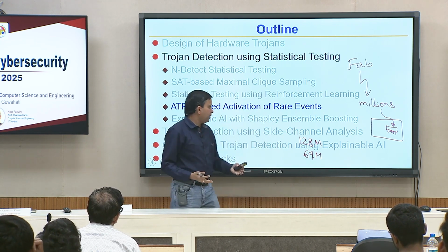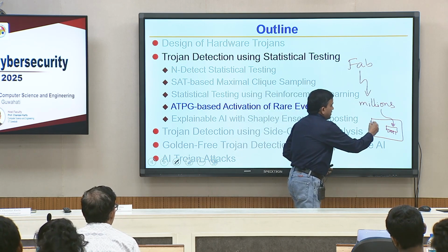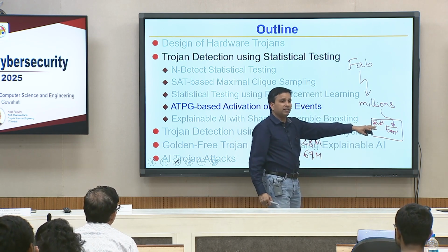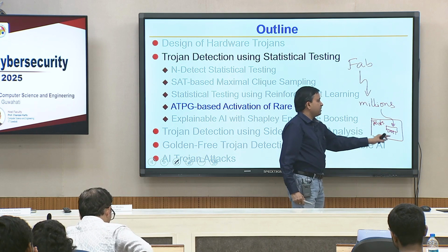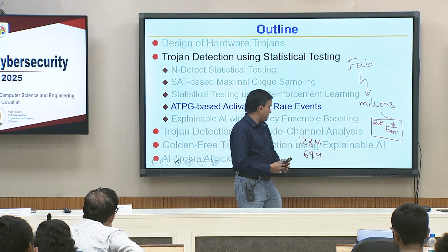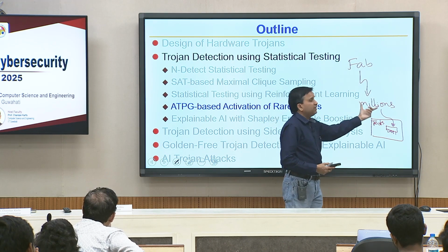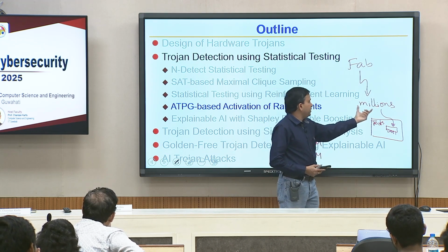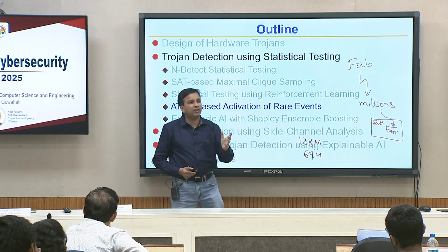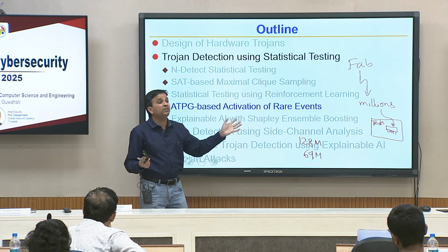So there are economic choices, but no matter what, the key point is the number of tests. The tests I generated based on controllability and observability are the tests sitting in that tester board. You put a chip in, run all these tests, and then throw the chip into the left bucket, right bucket, or the middle bucket where you sell it for a lower profit margin. So the number of tests is important if you can reduce it, because it is a multiplicative factor: you are going to run it for millions of chips. This is slightly orthogonal to functional verification, where you do it once, twice, five times; here you are going to do it millions of times.